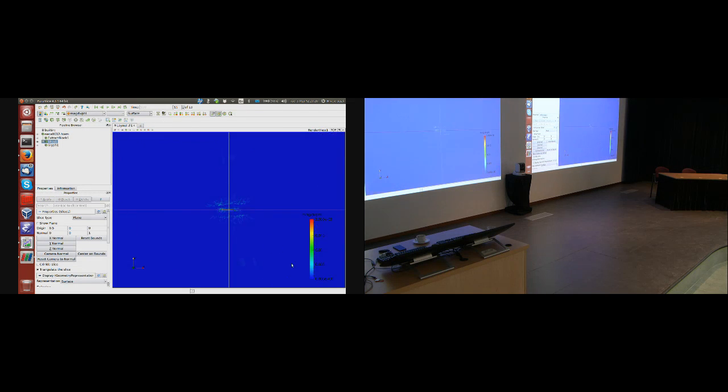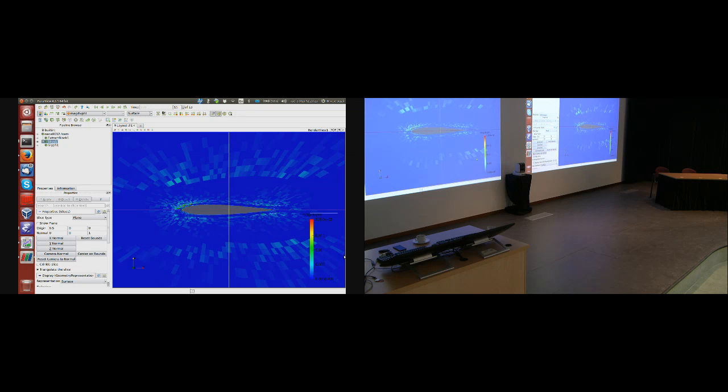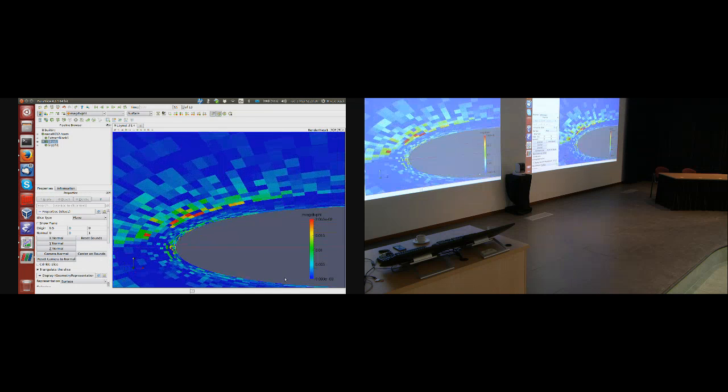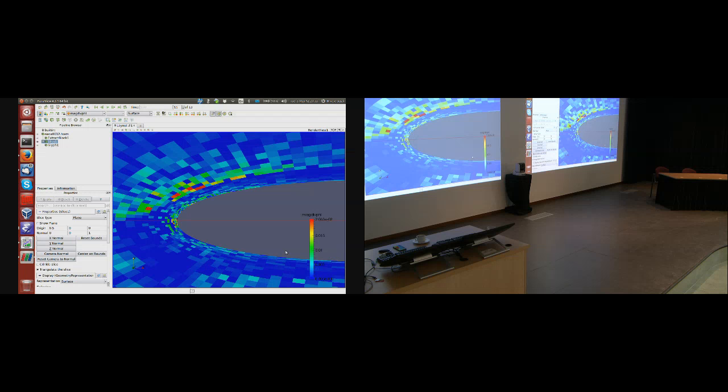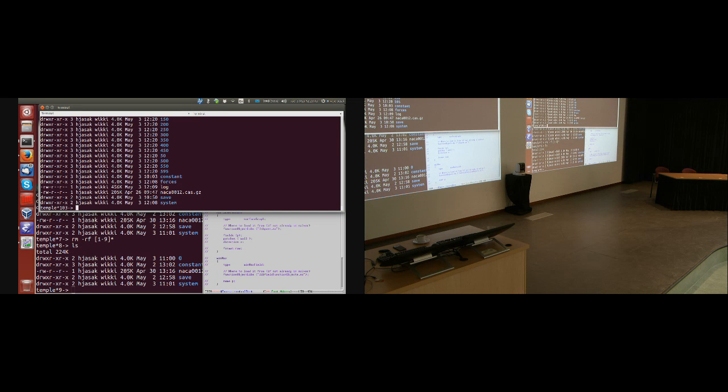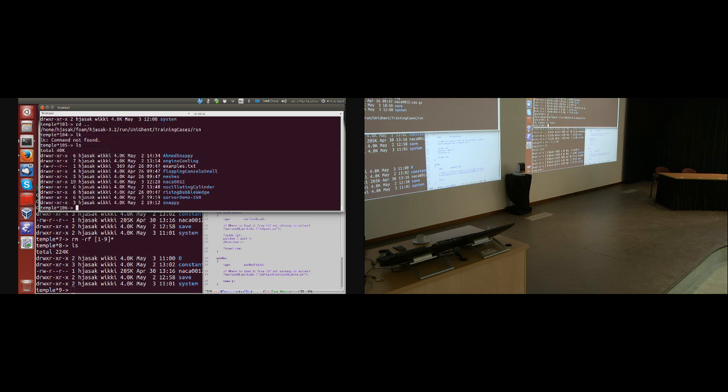Zoom out. And as you can see, this is basically zero. Okay? You will get a little bit of numerical garbage like this, but the divergence of the flux is zero, which is okay for an incompressible flow. Okay. What other things would you like to see with this case? Any ideas? No? Well, in that case, I'm going to give up. And I'm going to give you your job.